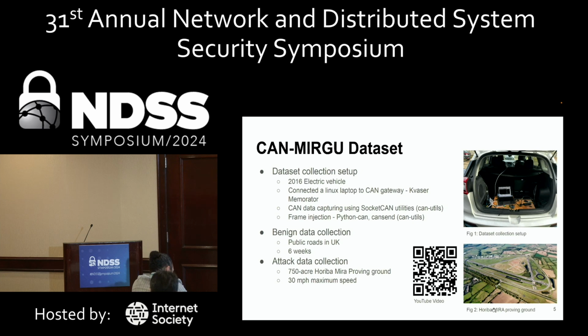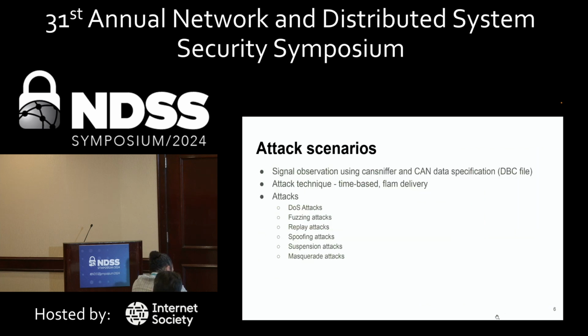We received access to the CAN data specification for some CAN IDs. Additionally, we observed the payload change using the CAN sniffer available in CAN utils. Based on this knowledge, we created our attack scripts. We used two techniques to inject malicious frames. The first one was the time-based technique. We injected malicious frames every 10th second. The second technique was the frame delivery. This means injecting a malicious frame with the same ID immediately after the appearance of the legitimate frame.